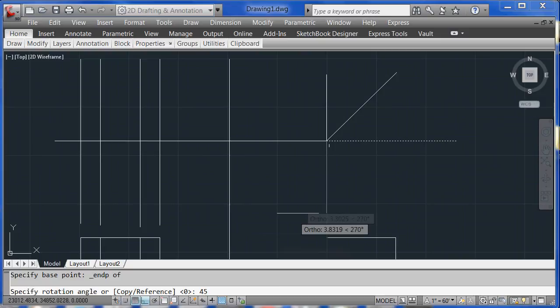So I'm going to use, here's a new modifier, shift right click, and I'm going to use midpoint. Shift right click, simultaneously midpoint. You go here, and here's where you type in either 0.75, or notice down here I have a diameter option.